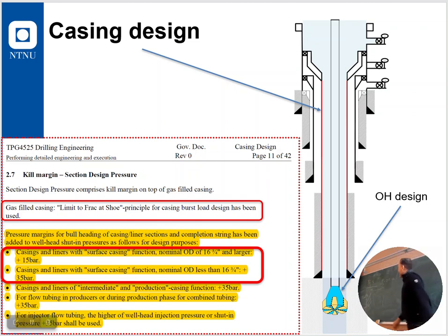Now, the highest pressure from the nature is what we described, but should you be in this awful situation that actually the whole casing is full of gas, right? It's not normal, but again, a load case is an extreme, and it's a design point. We need to go to the extreme to know that yes, it can hold it, right?